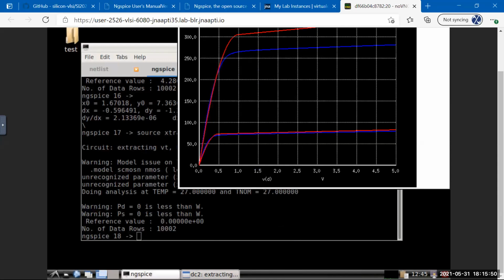For example, when we did the derivation, I said v is equal to mu times E, that is, the terminal velocity of your electrons is mobility times electric field, but it's not true for high fields. Once the fields get really high, your mu is going to saturate. In other words, your velocity is going to saturate.